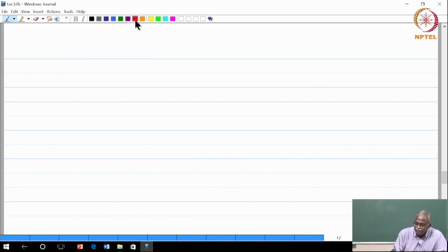Now, in the previous case, what was the bandwidth? 10 megahertz. Now ask the question: supposing my bandwidth had been 10 kilohertz instead of 10 megahertz, what would be the symbol duration? It would be 1 over the baud rate, which would be approximately 10,000. So the symbol duration would be 1 over 10,000, approximately something in the vicinity of 100 microseconds.